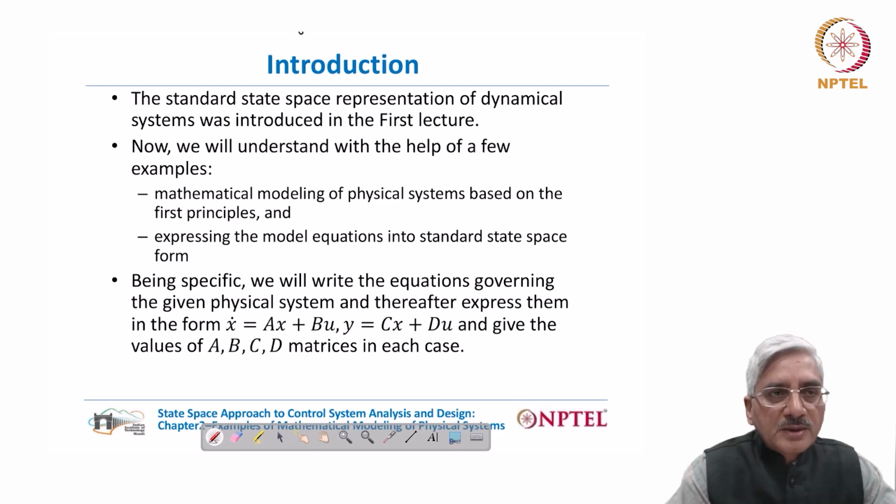Generally, the governing equations so obtained will not be directly usable by the control engineer. In the state space approach in particular, we want the model equation in the state space form. So, the governing equations are to be put in the standard state space form.